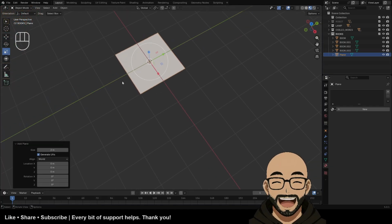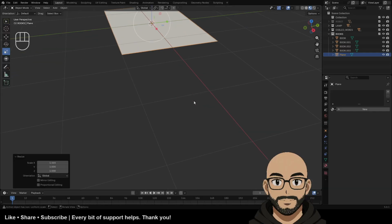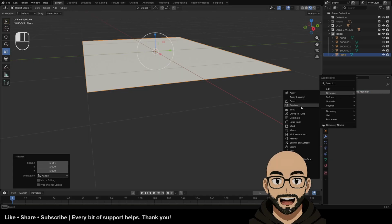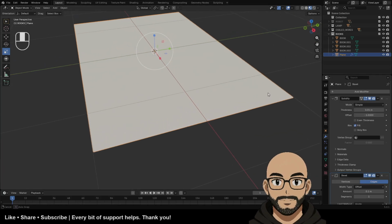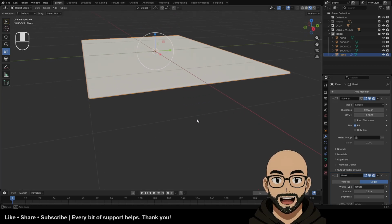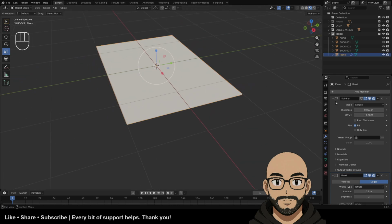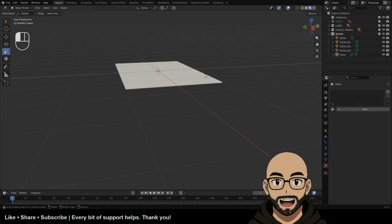So we got a plane, and we're going to scale it up so it's almost like an A5 page. We're going to add some thickness, so we can just add a solidify. I'm going to add a bevel on that, just around the edge a little bit. Maybe make it a tiny bit thicker. There we go. I'll leave the material, as we'll put a texture on that later.